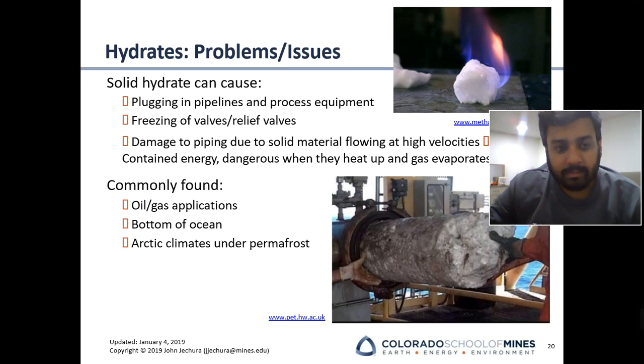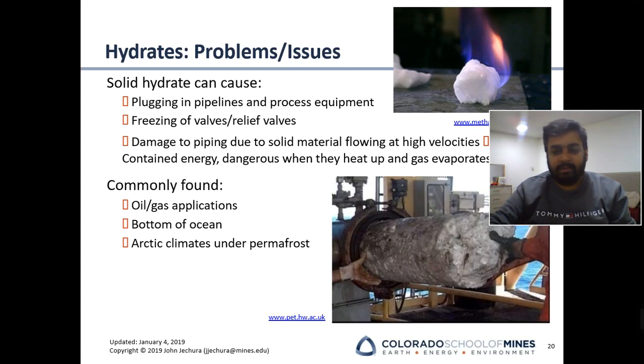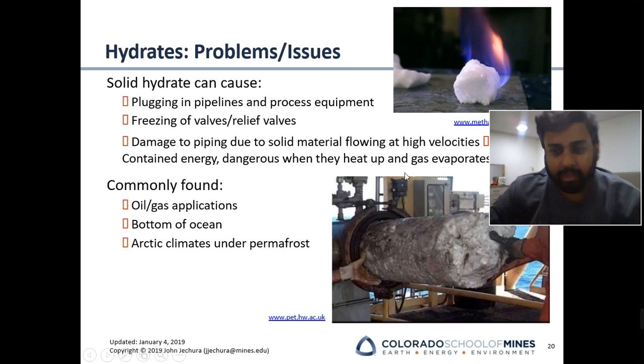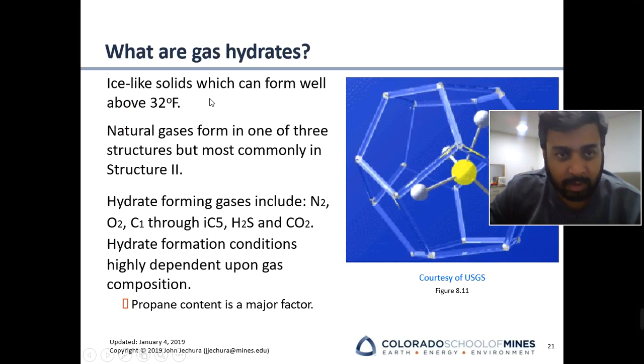If the gas has some water, it can cause hydrates, and a hydrate is like ice, a crystal-like material, like the white material you have in your refrigerators. The same kind of material can be formed from this gas, and this gas is made of methane, so it can even burn. You can see here it can catch the flash. So hydrates can be very problematic, and we have to make sure that we remove these hydrates from here. So what are the gas hydrates?